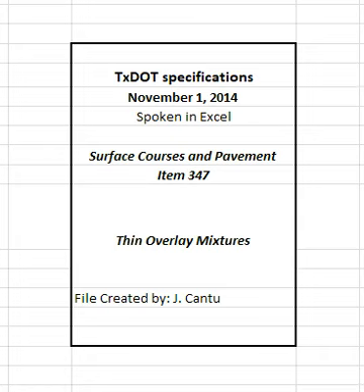4.4.2.2.4 Ignition oven correction factors. The engineer will use the split samples provided by the contractor to determine the aggregate and asphalt correction factors for the ignition oven used for QA testing during production in accordance with Tex-236-F.